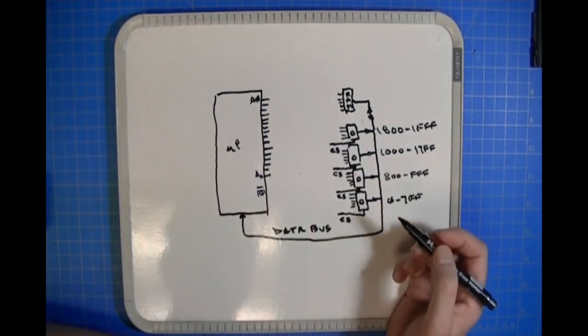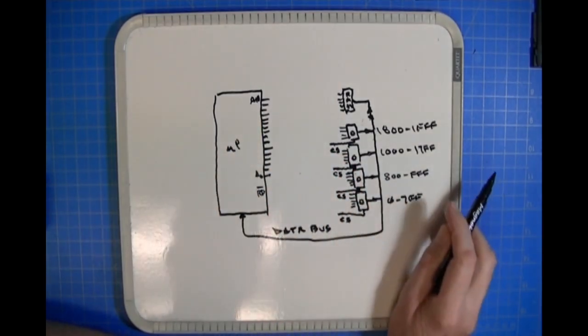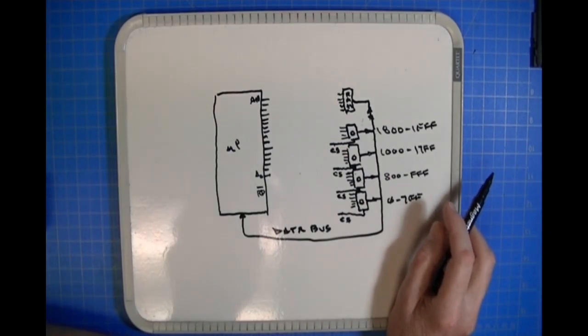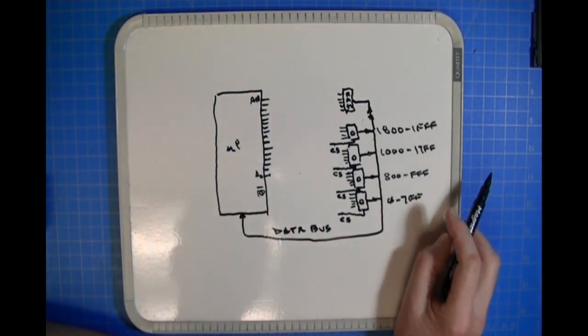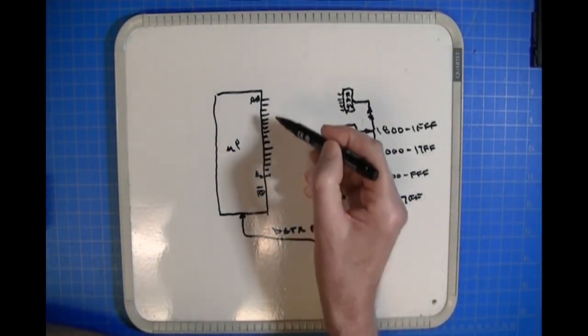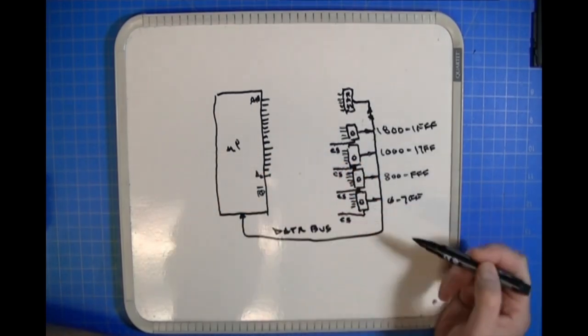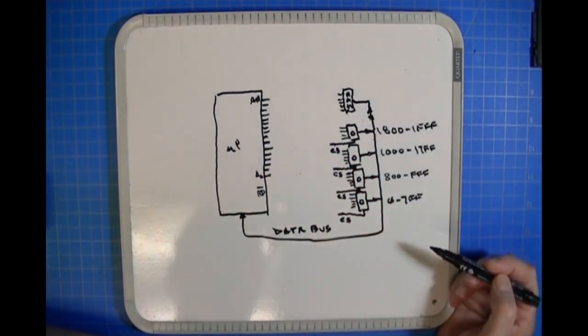In the case of the address at the very tippy top, 65535, since this would be a 16-bit integer, the address bits are all going to be 1s. And in between there, you're going to have a combination of 1s and zeros that will determine what address is being accessed by the microprocessor.